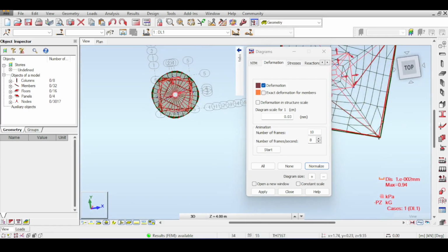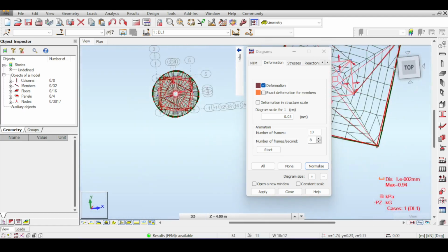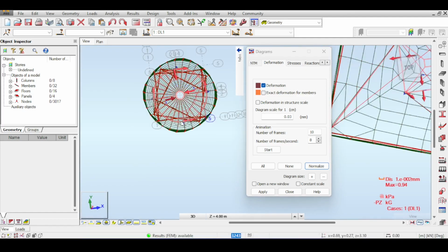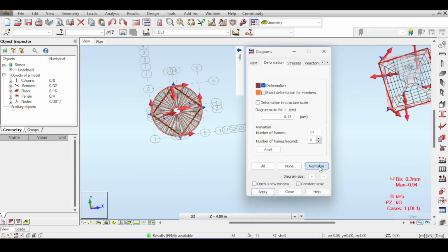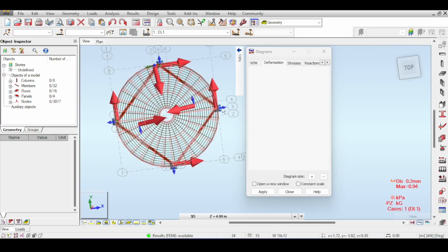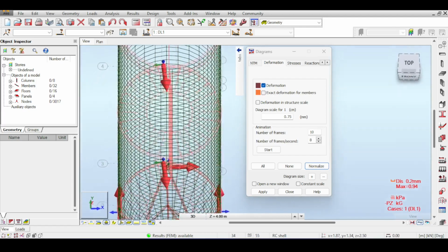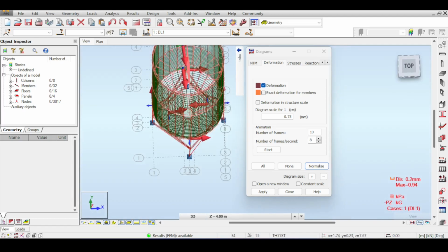Also, it's consistently bulging, and I have a reason for that. This is really interesting. Why is it not bulging exactly the same on the circumferential side? Because you have supports, and those supports stiffen parts of the circumference and release parts of the other circumference. It's also the same here. So, yeah, let's normalize back and continue. Because when you have those supports, when it bulges, it doesn't bulge out exactly the same in all the directions, because there are things holding some of the directions, so it doesn't bulge exactly the same everywhere.